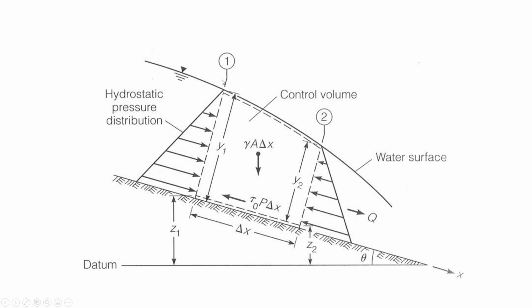I want to jump straight into this discussion. Non-uniform or unsteady flow would cause this kind of a profile. So let's just see what we're looking at. There's a horizontal elevation datum against which all of the depths and elevations are measured. And then here's the bottom of the channel.